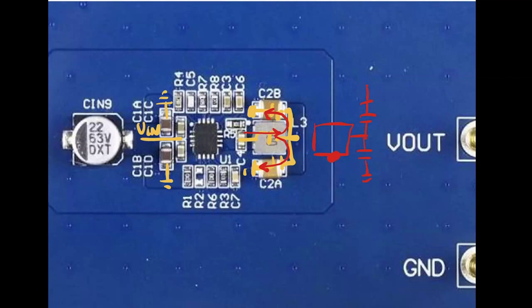Every time you have inductors, including inductors with closed cores like toroids, they are really good creators of magnetic field through leakage, or they can attract a magnetic field very easily. So it's impressive how you can destroy the efficiency of a filter or a system with this kind of location.